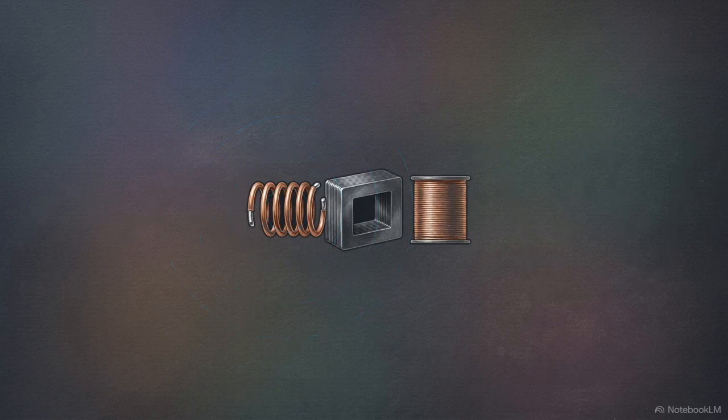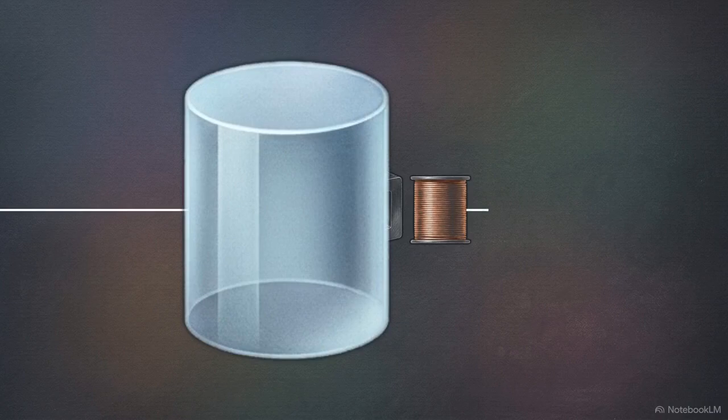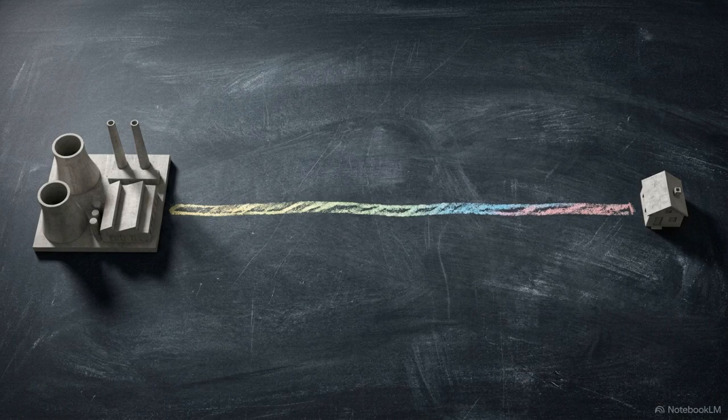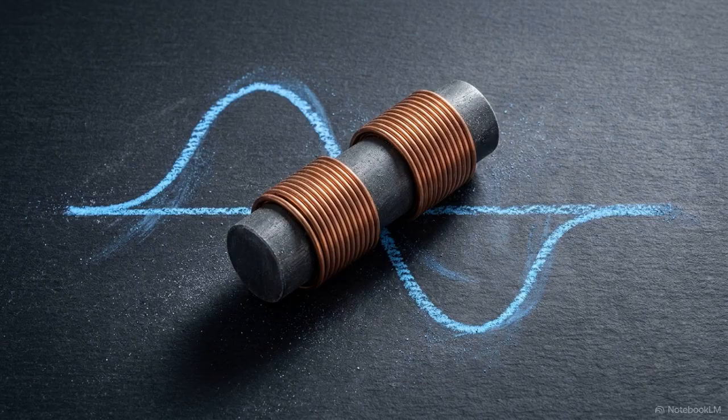Direct current functions differently. A flat, continuous flow of DC electrons creates a completely static magnetic field. Because a static field does not move, it cannot induce voltage in an adjacent wire. Direct current cannot be stepped up or down through passive induction. Without transformers, a power grid is trapped. Whatever voltage leaves the generator is the exact same voltage that must travel to the end user. The geometric curve of the sine wave provides the physical conditions necessary to manipulate electrical pressure.